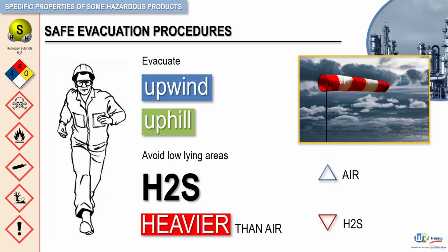Recall, evacuating employees must report to a designated briefing area so each person can be accounted for. Briefing areas should also be set up at least 250 feet away and upwind from hydrogen sulfide-prone areas. These briefing areas will have prominent signs that can be easily seen by employees. Remember that a high percentage of hydrogen sulfide deaths involve multiple fatalities.